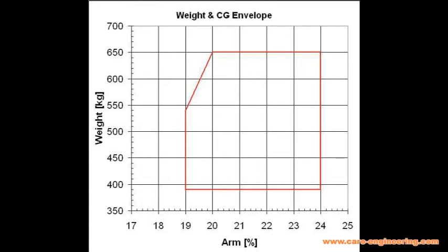The range shown here from 19% to 24% is a good range for any conventional small airplane, although there are cases when the CG can be safely moved further forward or back. You can use this range or something a bit wider to start with. The final CG limits will be determined during flight test. In order to calculate the CG from the fuselage mass table, use the same procedure as explained before by calculating the moments. Of course, the CG never comes out right to start with, so you will have to shift some weights around to make that happen.